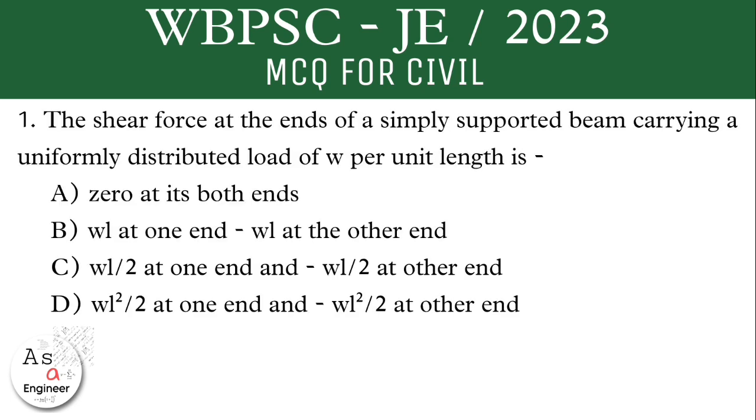The shear force at the ends of a simply supported beam carrying a uniformly distributed load of W per unit length is. The correct answer is option C, WL by 2 at one end and WL by 2 at the other end.